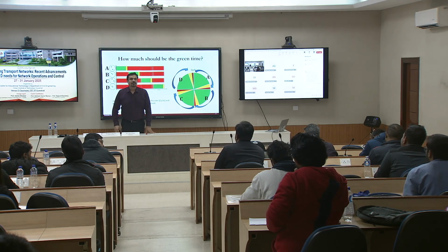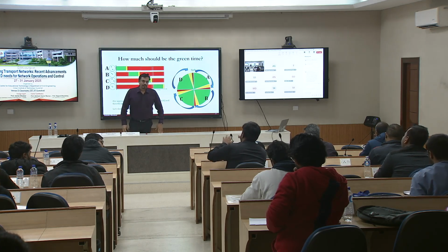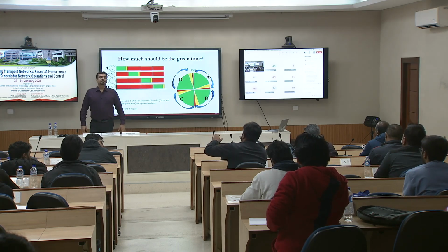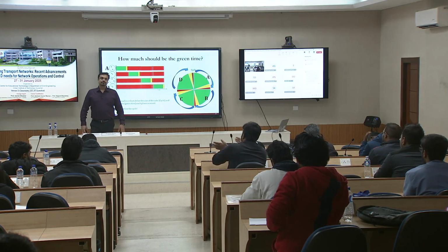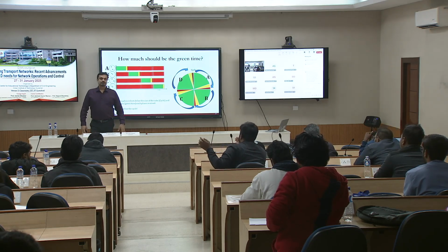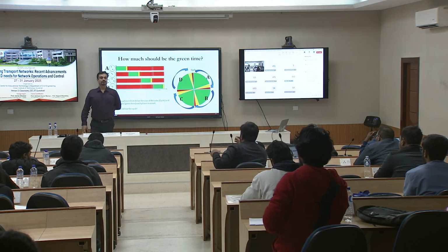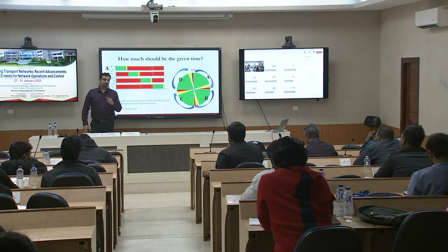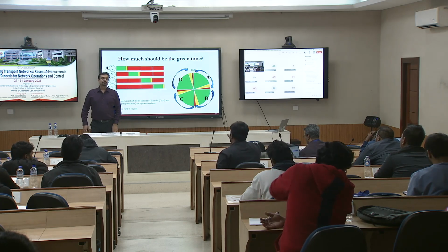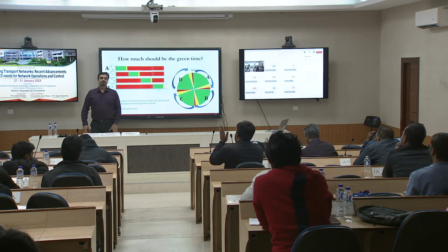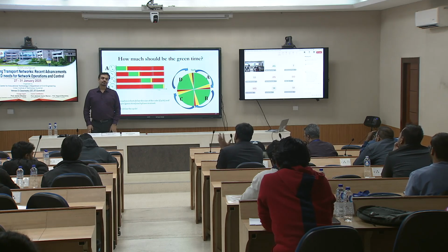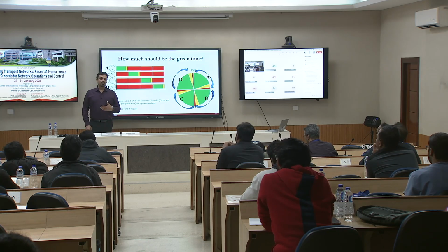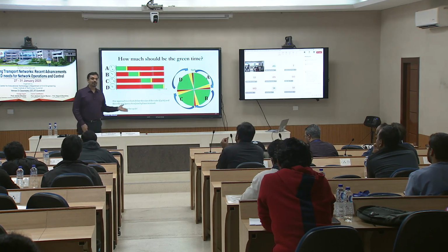Sorry, there is a loss in the green time because of the queue at the intersection. So in that scenario, the queue time will be there, and suddenly green might come in that moment, and mostly it cannot flow upstream. So some seconds have been lost. So you're saying that when the signal turns from red to green, the vehicles don't enter straight away, there is a loss happening. I'm coming to that.